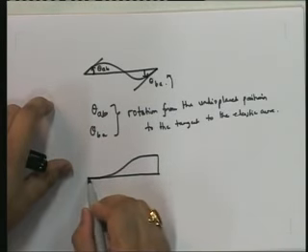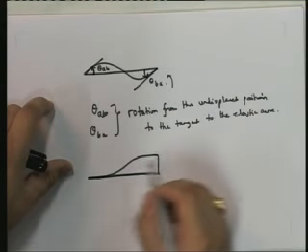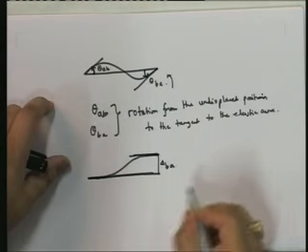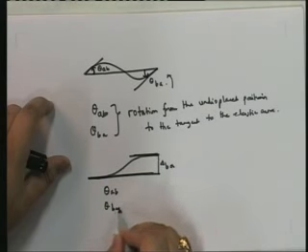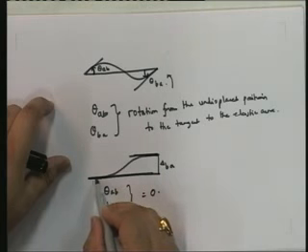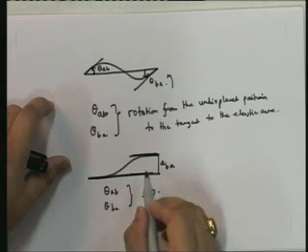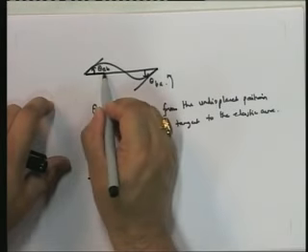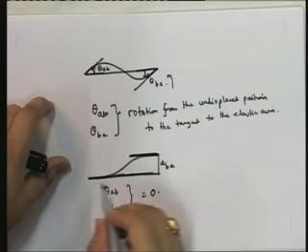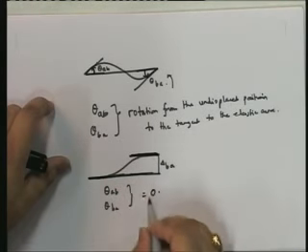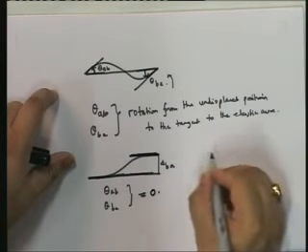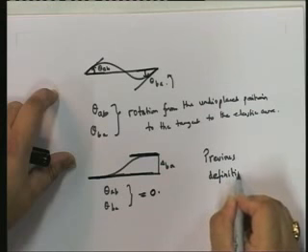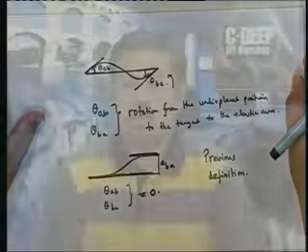When we have a displacement, what is theta? From the original to the tangent. So, in this case, when you have delta B A, what is theta A B and theta B A? Both equal to 0, because the tangent to the elastic curve at both positions is the same as the original tangent. So, they are equal to 0. This is the previous definition that we had. Today, I am going to introduce you to a new definition.